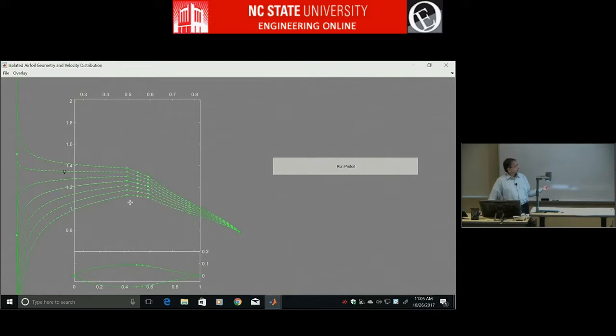This is called a transition ramp. And we'll talk more about this. This is called a transition ramp because it's intended to be a ramp that transitions from favorable to adverse, and instead of having a sharp joint, you have a little smooth curve, just like a highway ramp. You go from a local road to a highway, you have a ramp, right, where you smoothly increase velocity. Like that, this is from a favorable gradient, you can go to an adverse gradient with a nice ramp.